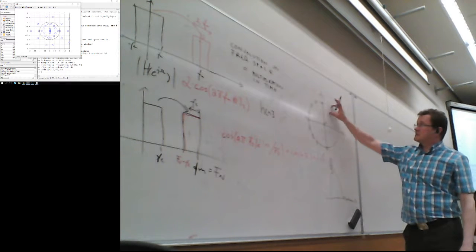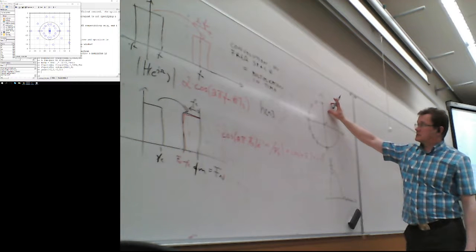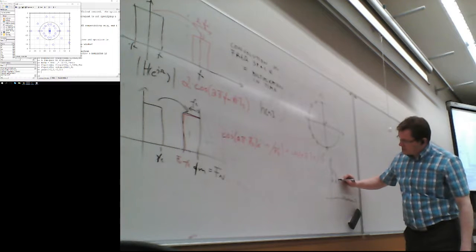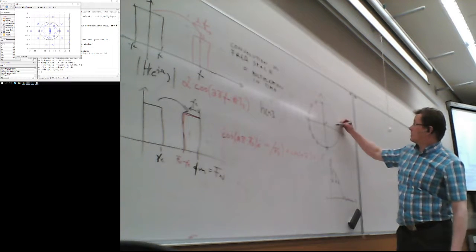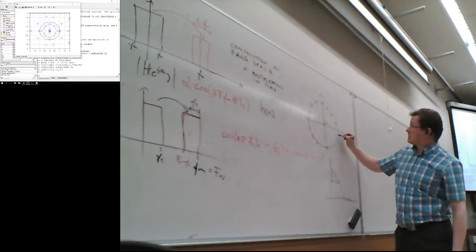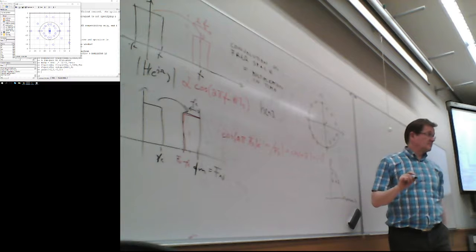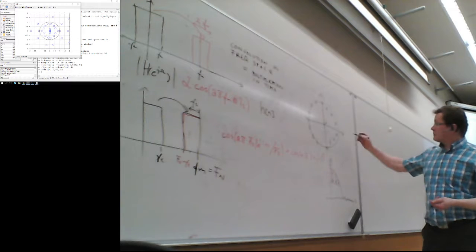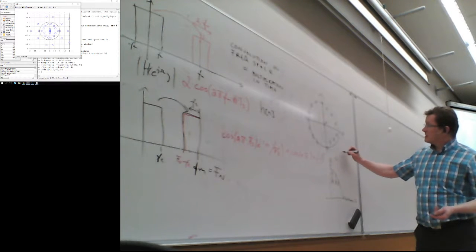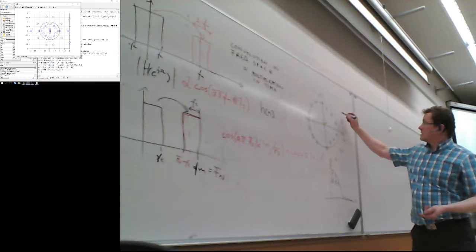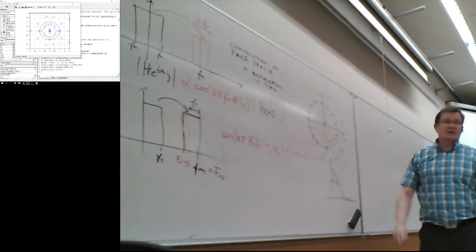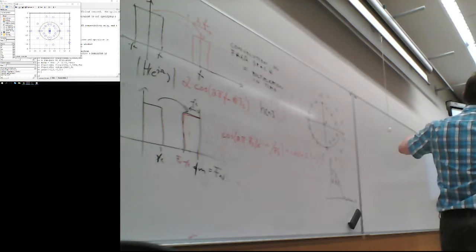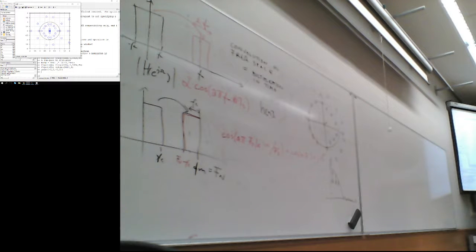The only way is to put some zeros here, but not on the unit circle, but close to that point, so we can actually pull some frequencies down, like putting those here. Okay, but then basically it will go like that. But on the other hand, for the symmetry, you also need the reciprocal pairs of those poles here, not the zeros. So that's why we have them on both sides.